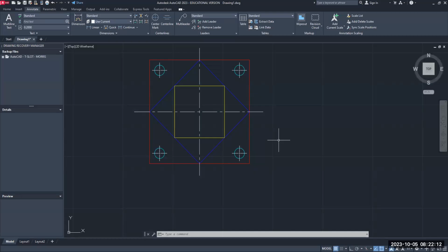Yes. All right, now what I'm going to do is I want to dimension this. I've already got the center lines located. The dimensions, if you took a picture of it, you don't have to, you can just follow me, but we have to put some dimensions here. See right here, dimension, right next to dimension, there's one called linear. Please select that.